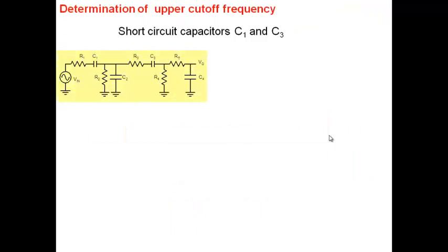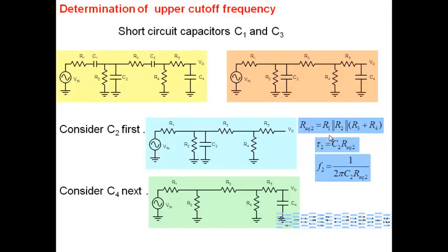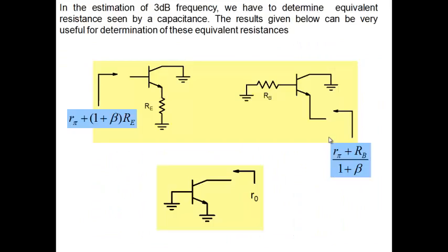If you recall, all transistor capacitances will be open circuited. While we do the lower cutoff frequency calculation, we've been saying that these results are useful results. From henceforth, unless we are forced to, I don't want to draw a hybrid pi model and look at circuit analysis at that level.